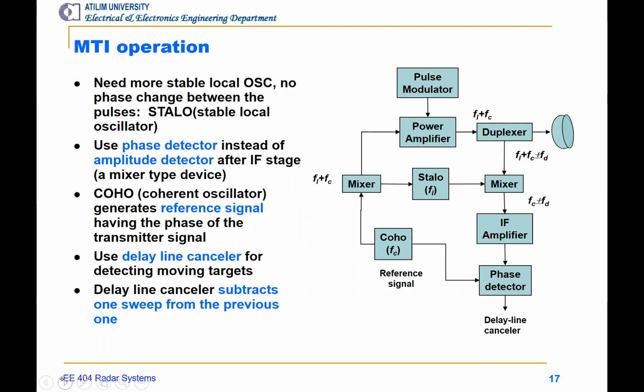So whenever there is a phase variation, we expect Doppler shift. So if there's a phase variation due to the system, then that's going to be an error in Doppler shift. Okay, this is why we call it a coherent system, a system very well designed for such phase ambiguities.